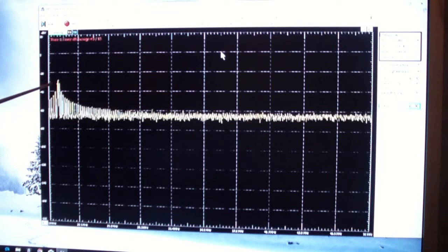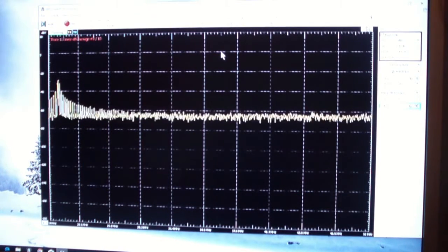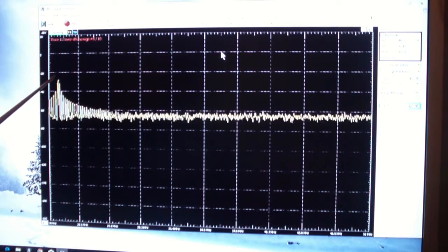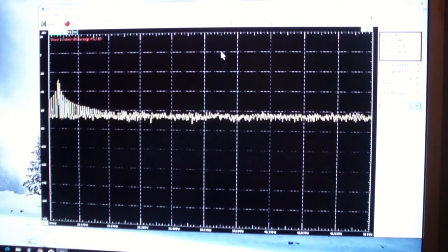Well, the problem is that on the Analog Discovery, since it only has a 50 megahertz bandwidth, you can look at the fundamental and its sidebands, but you can't look at the second or third harmonic of the carrier and its sidebands. And of course, those are important in complying with FCC specs and so on for transmitters.